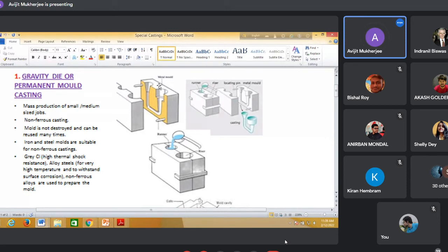and to compensate that sinkage, extra material is needed. So here, I don't require to provide gate, riser time and again, because already in the permanent mold, it is prepared. Metallic mold. So all these are prepared. Only when these two parts are united here, things are ready.